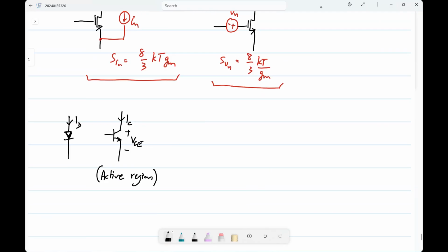So what happens is that these charges in BJTs, or these electrons in vacuum tubes, are not fired at some uniform rate. There is some average rate, but the timing is random, and it follows what is known as the Poisson distribution. We don't have to get into the details of that. Because the timing is random, if you look at the instantaneous current, it will have noise as well. Compared to the average current, there will be some fluctuations above and below that.